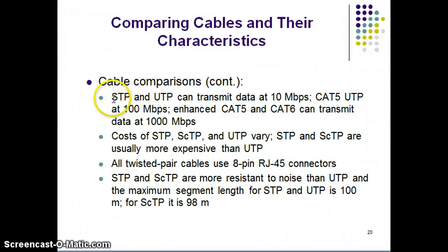Here again the acronyms, remember those? Shielded twisted pair, unshielded twisted pair, some of the speeds that they're talking about. Here's that screen twisted pair. Okay, some of the distances. And our standard in the industry, we typically use Cat 5E or Cat 6, unshielded twisted pair, and it's good for 100 meters, period, not to exceed. So that's kind of where the standards are.